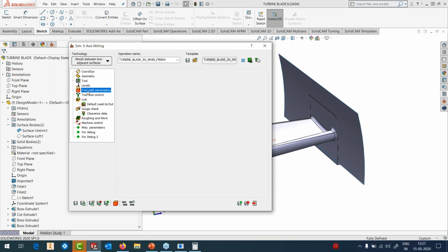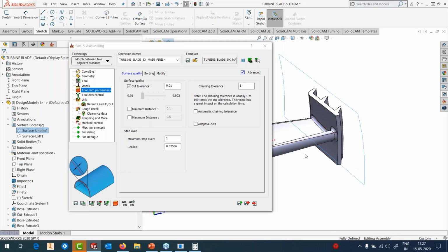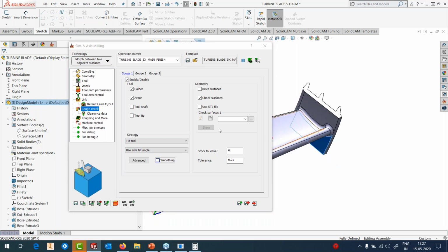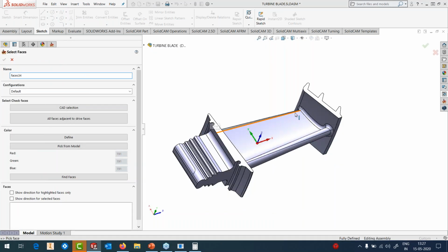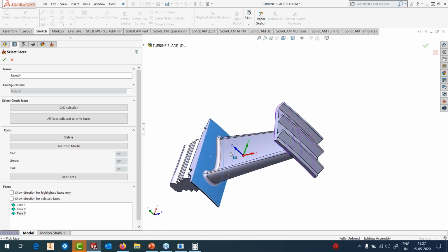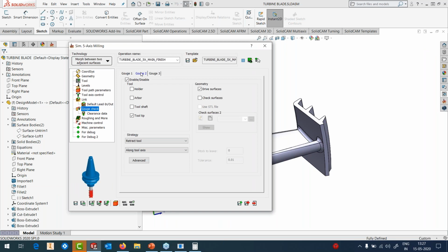Okay, so in the toolpath parameters, everything is done. Only thing now, the function of that face is over. I'm going to switch it off, and let's go to the gouge check. And here I'm going to enable the check surface. Basically, the check surfaces are these surfaces where I would like the tool and the holder also to tilt if they get too close or if they get precariously close to these surfaces. Okay, this is done. And the second check that I've put is for the drive surface, wherein I've said retract the tool along the tool axis if you find any collision with the drive surface. With the first group of surfaces, I said tilt, second retract. Okay, that's all that is needed.